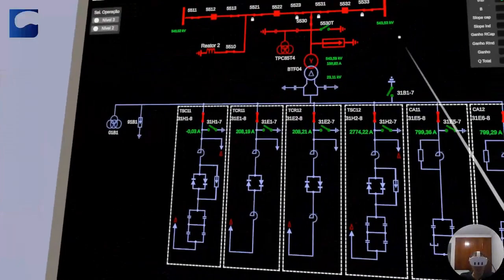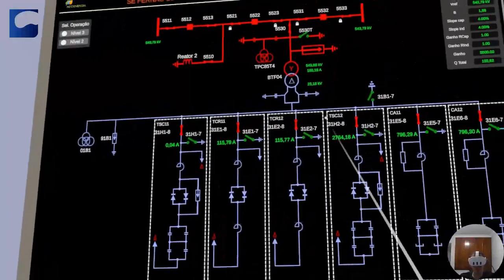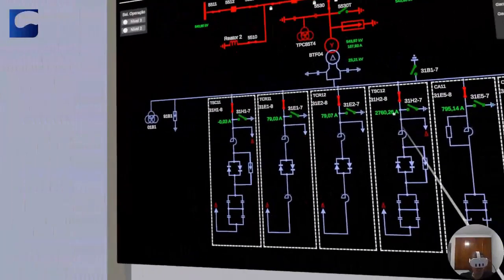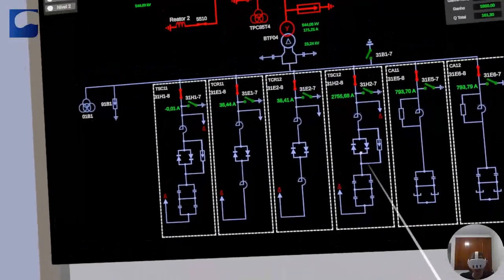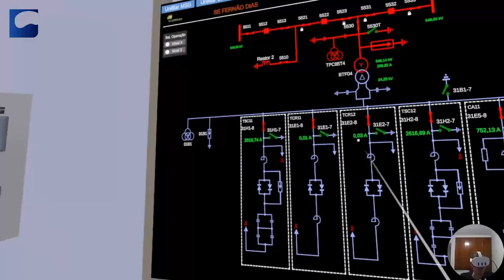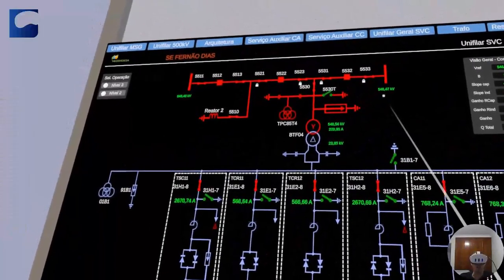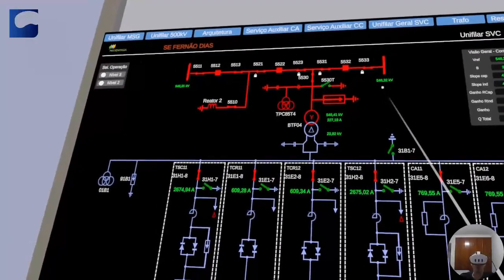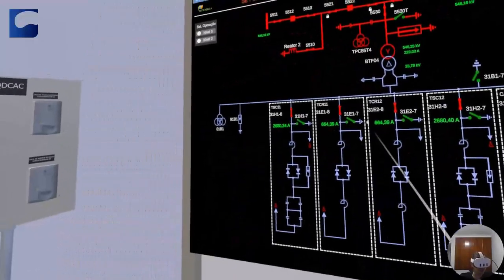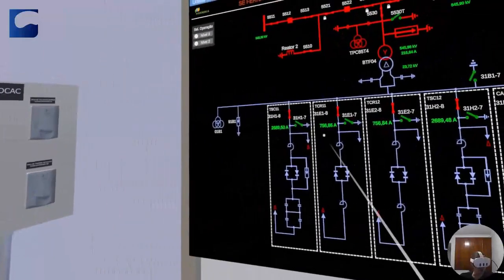So, to raise the voltage up to 545, what did it need to do? It had to switch on the capacitor. So here it is. It switched on this capacitor, and now it's switching the reactors, with the goal of reaching 545. So it's here chasing the set point of 545 and switching the reactors and capacitors to reach that value.